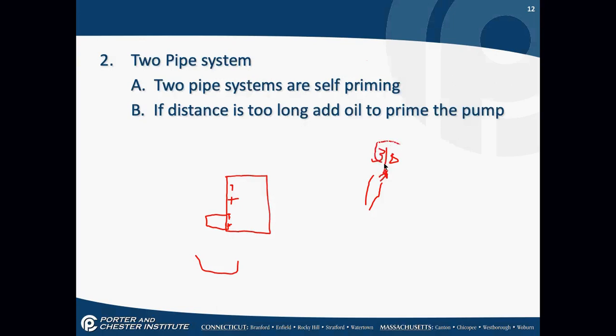Remember the other day, you might have missed it, I said this FF terminal is the exact distance apart where you can take that 3/8 inch open-ended wrench that you've used to open that oil bleed valve, and put it across those two terminals. It will keep the burner running while this valve is open.